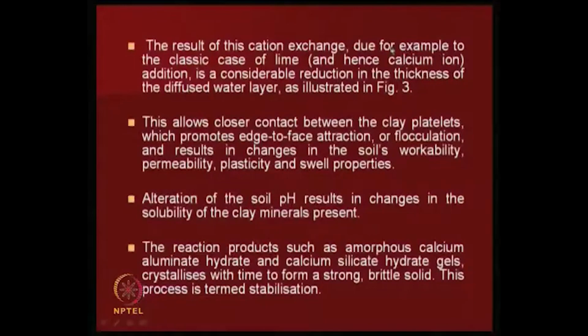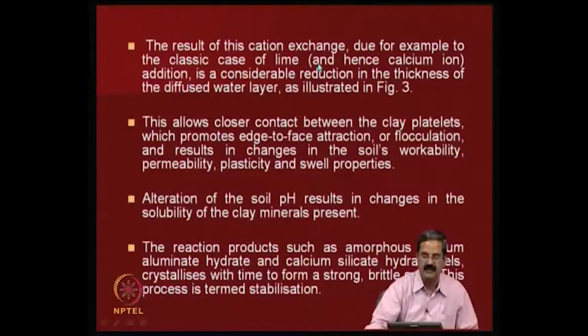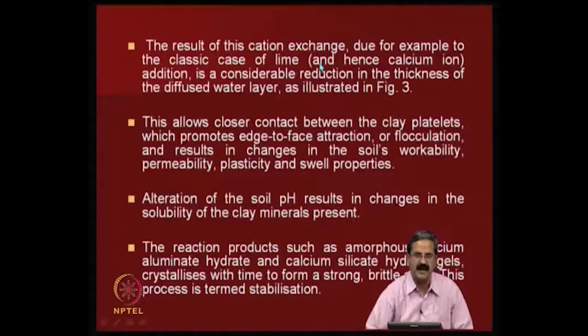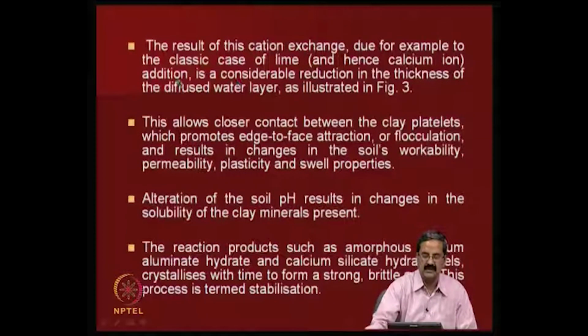The result of the cation exchange is the classic case of lime, we know that. So, why do you add lime here? That is essentially because it reduces the diffuse double layer thickness, and that is what we know. Not only that, this allows a close contact between the clay platelets which promotes edge to face attraction or flocculation and results in changes in properties: workability, permeability, plasticity and swell properties.